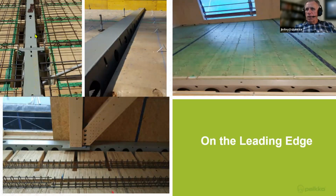Now here, you can see this gap. This is going to be filled with concrete right here, and you can see the rebar. So these are various ways that the timber concrete composite deck is tied, the concrete to the wood. And you saw these are older ways now, and you saw the Nilco that is looking to replace this.